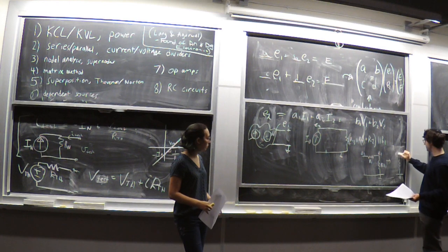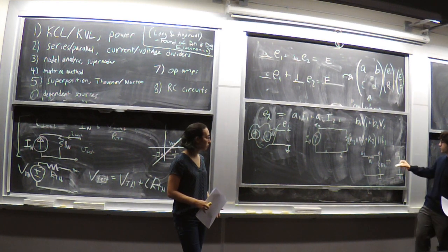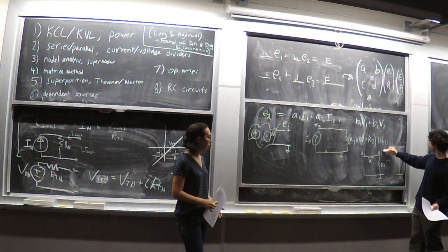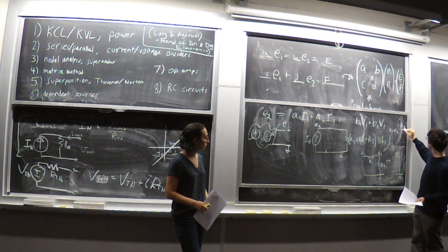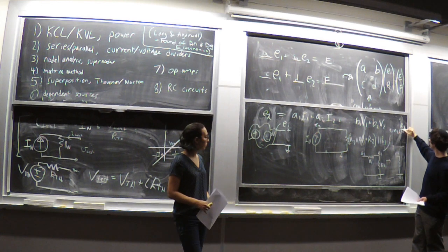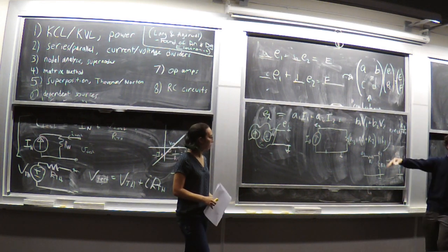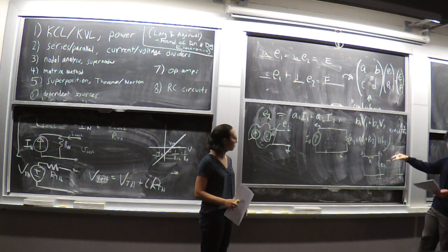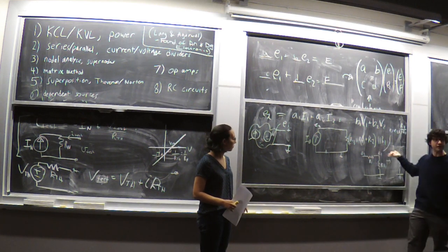And this would then be E2. But if I wanted to keep track of what E1 was, well, this is like a voltage divider like we talked about earlier. So I could say right here that E1 equals E2 times R2 over R1 plus R2. So now I don't need to keep E1 around anymore in my circuit, because when I eventually solve for E2, I can just plug in for E1. And then I might have expressed E2 in terms of E3 because I consumed it and so on and so forth, but you can keep track of all of them as you're going.